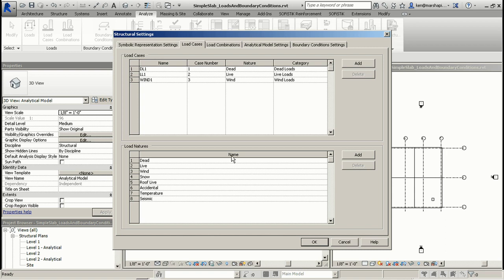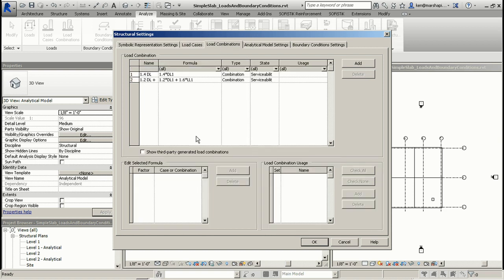Oh, it's a checkbox in each load case. All right. So in the Sofistik tool, Thomas just said that it's a checkbox in each load case, so you can decide for yourself whether you want to do it or not. So we have the ability to pre-create load cases as well as combinations. So I can create my load combinations directly in Revit. Now this is not the thing that you want to do yet. Hopefully there will be some tools to help facilitate this in the future.